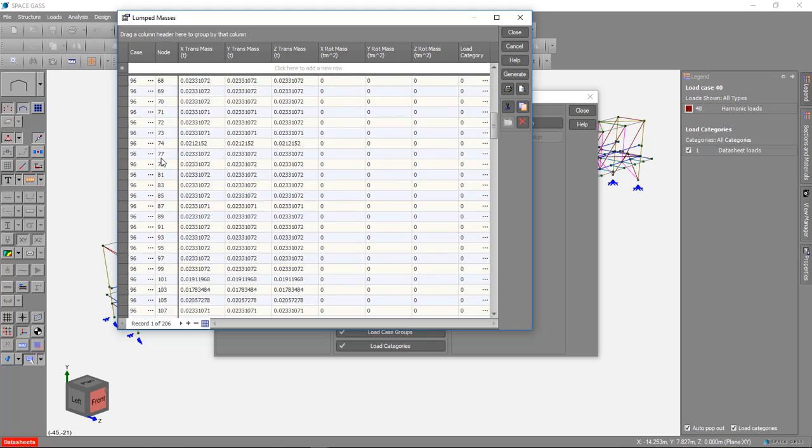you can see that we've got some masses in various load cases here, and these represent the masses that contribute to the inertia of the structure. So there could be things like mass due to dead load or live load or anything else attached to the structure. You'll also notice that we've used the same value in the X, Y and Z directions. If the vertical axis is Y, you'd probably think normally the mass is just a vertical mass, but when the structure is vibrating, the masses also have inertia in the 2 horizontal directions, so that's why we put the same value in all 3 directions.